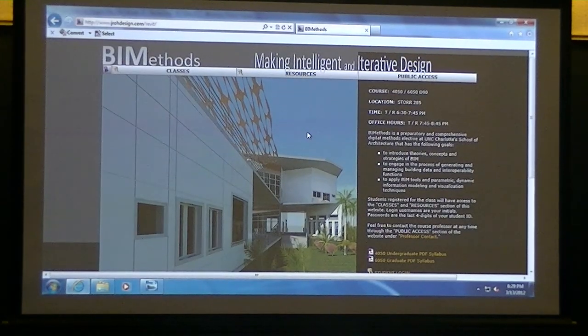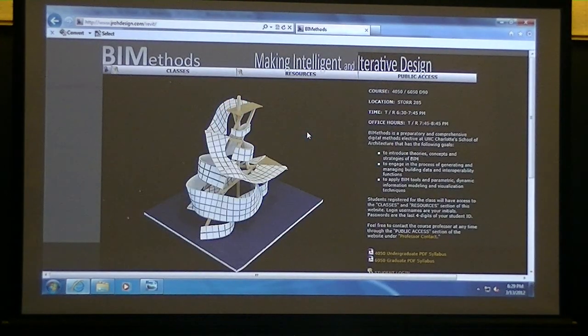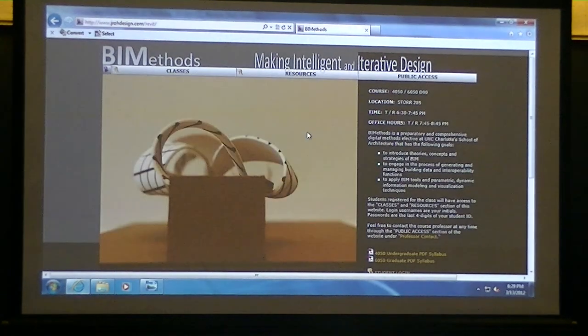Can't get the void to work. Try to build, you know how in the last class with the adaptive component, instead of making it solid, I built up the shape of the faces. You might try building it up that way, making a void, working around it. Yeah, but I'll check out what's going on. Sometimes the void just needs to make sure it can cut through something.